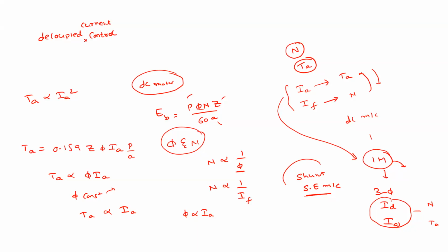So decoupled control of the induction machine is possible, which is obtained by direct torque control or vector control. By using these two techniques, we can control the starting torque, the steady state torque, and seamlessly control the speed of the machine. This is the basic idea of how decoupled control originated.